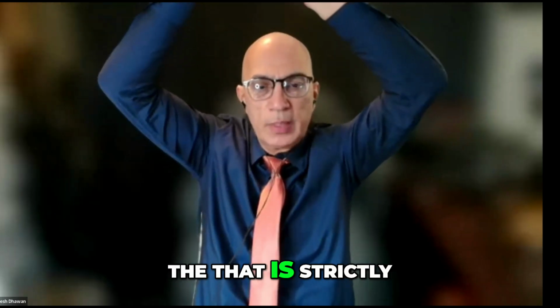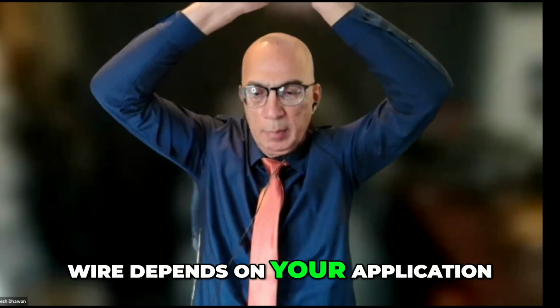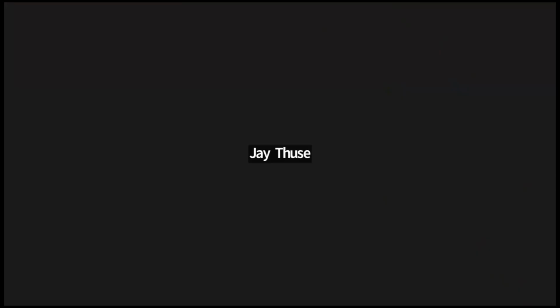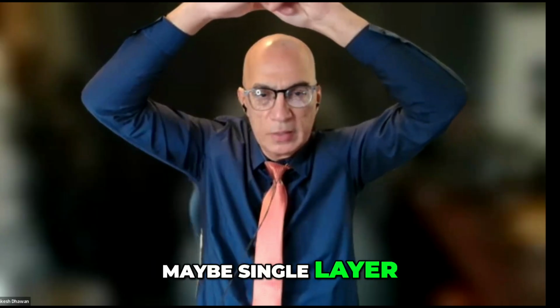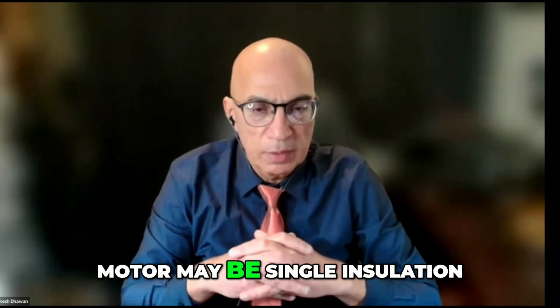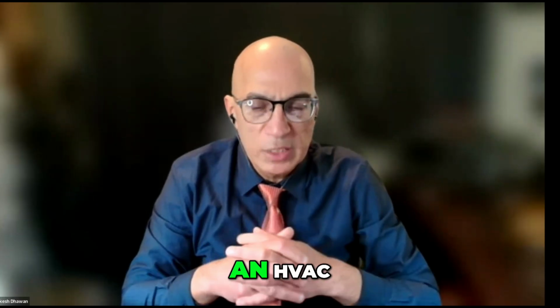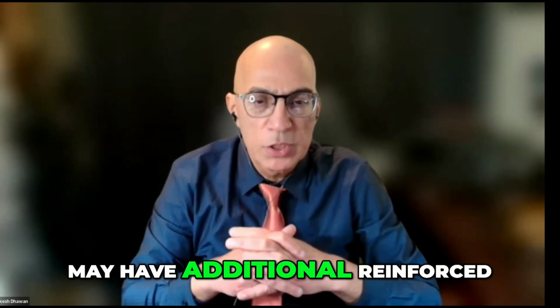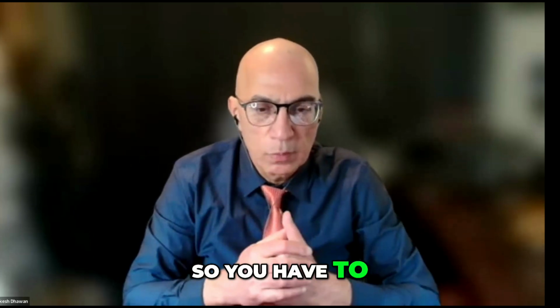No. Whether it is strictly insulated or double insulated depends on your application. If you have, for example, a commercial grade motor, maybe single insulation; industrial grade, maybe double insulation. Something which you use in HVAC may have additional reinforced insulation.